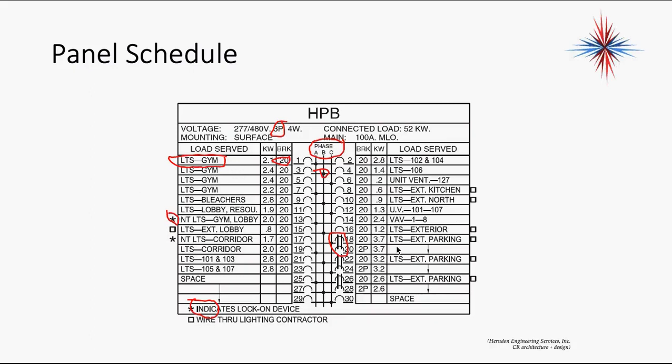So that's what's in a panel, and that's why, again, if there's an AC condenser that has a double pole breaker, that's your outside unit. If it's only rated for 20 amps and the condenser you need has a label on it that says 40 amps, you have to have a conversation with somebody because you can't install it on that circuit. It's not going to pass code and it's not going to work properly.